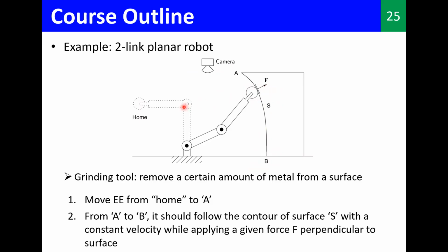But what is the input of this manipulator? The input is only this motor here, this revolute joint, and this revolute joint. So we have to control this in the required manner by controlling these two motors. There should be some mapping that we need to understand. When this motor rotates at some RPM and this one rotates at some RPM, there will be some Cartesian, or three-dimensional, velocity for the end effector.